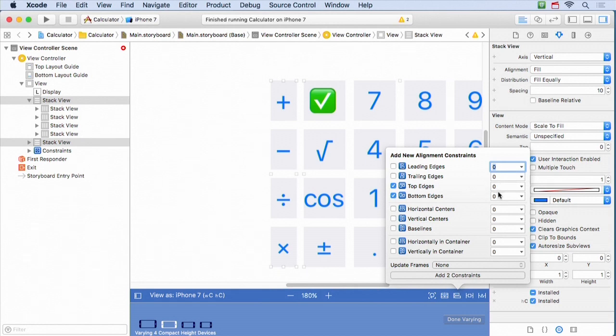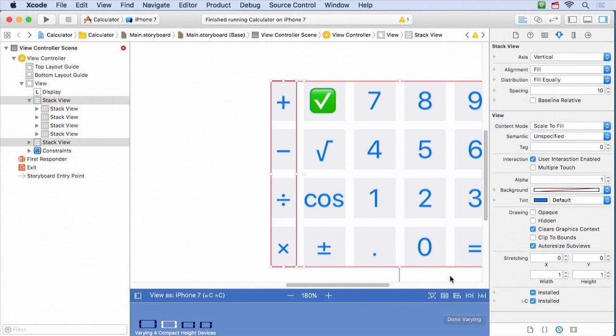These numbers over here, by the way, are an offset. So if you wanted it to line the tops, but you want one to be 10 higher, you could put a 10 in here. But I want them to be right along the top. I want to have the constraint where this is exactly the same and this is exactly the same at all times. So I pick whichever I want and just say Add Constraints, and I added them. Now, whoa, it turned red.